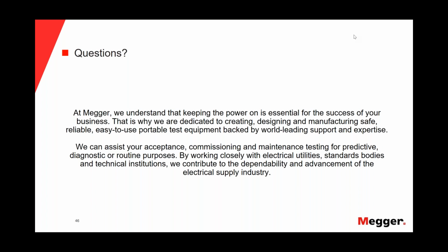I would say yes. In the vast majority of cases, we will need to disconnect both ends, because otherwise we could have some PD activity at the far end, for instance, and maybe we will not be able to know if the PD activity coming from the far end is because we left the cable connected or because we have problems in the termination. So I would say yes, it's necessary to disconnect the cable at both ends.